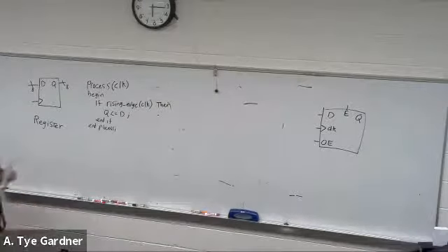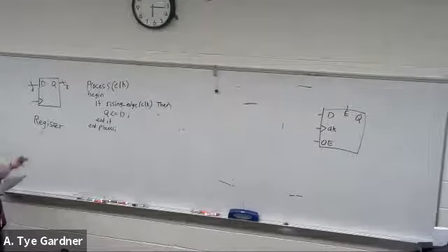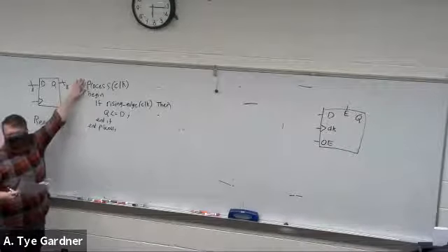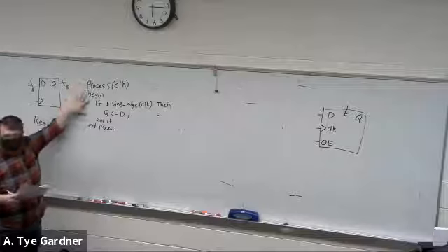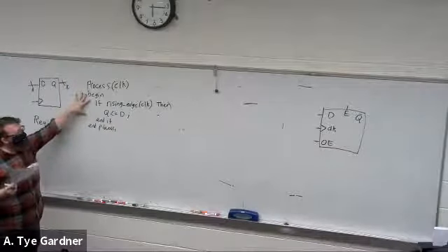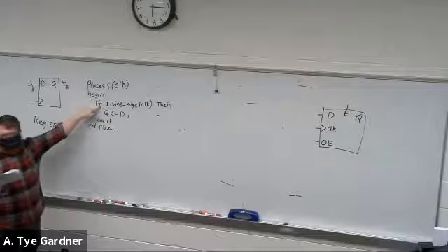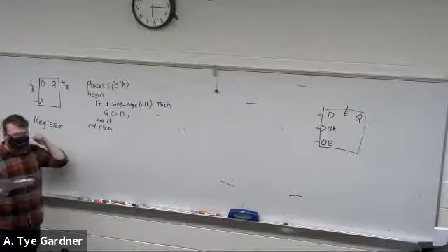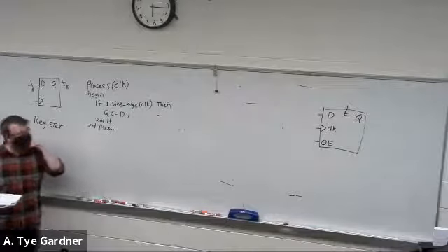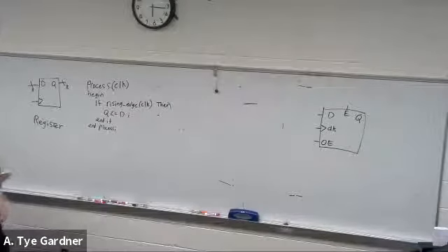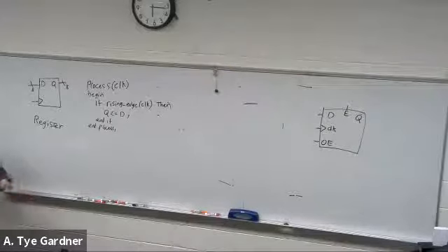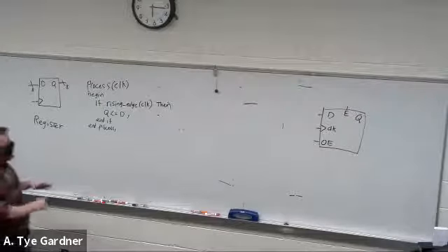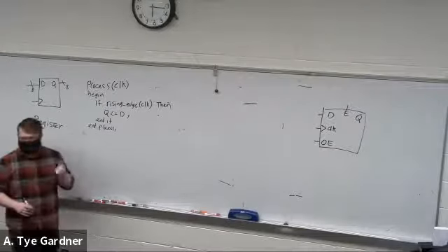All right, so what happens now is every time the clock changes, this runs. But if and only if it's a rising edge will it actually execute what's inside this if statement. Should we add an and enable as well? Yes, you can. And in fact, what you'll start to see fairly often is embedded if statements.